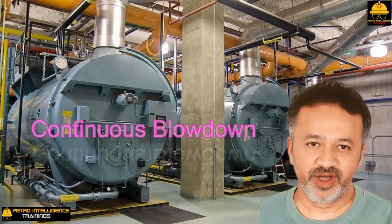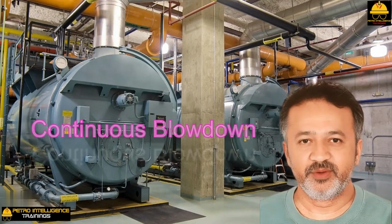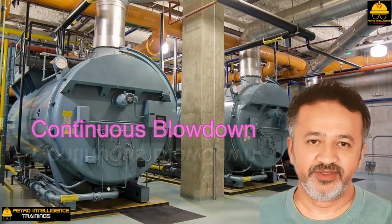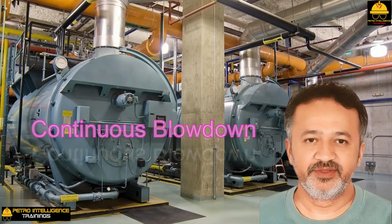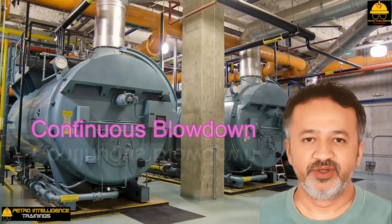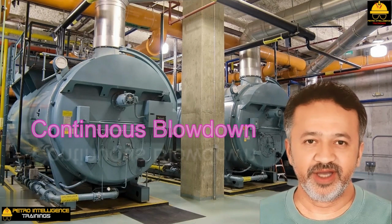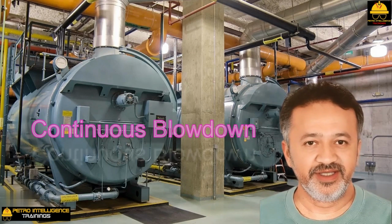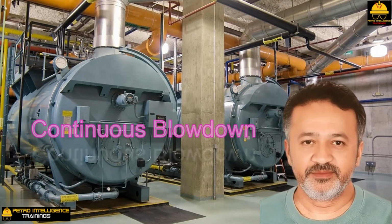If steam from a kettle waste heat boiler will be used saturated, for heating, reboiling, or stripping, then the TDS content of the steam is not particularly critical. If steam is used to drive turbines or will be superheated, then the TDS content of the steam is quite important. A good target for silica is 0.02 mg per liter silica in steam used for turbines or for a boiler operating from 300 psig to 600 psig. 0.4 total caustic alkalinity as milligram per liter of silicon dioxide in BFW.